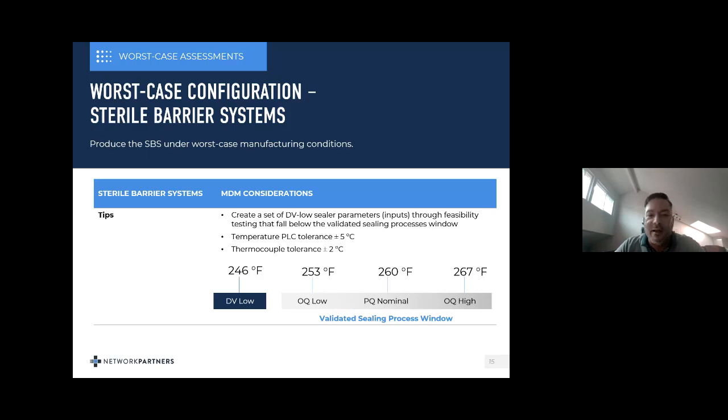Great question. And I've seen this time and time again where I do everything in one shot. So typically what I've done is use negative 18 degrees, and this is under ASTM D4332. And then I believe worst case was the humidity. So then we use tropical, which is 40 degrees C at 90% relative humidity.